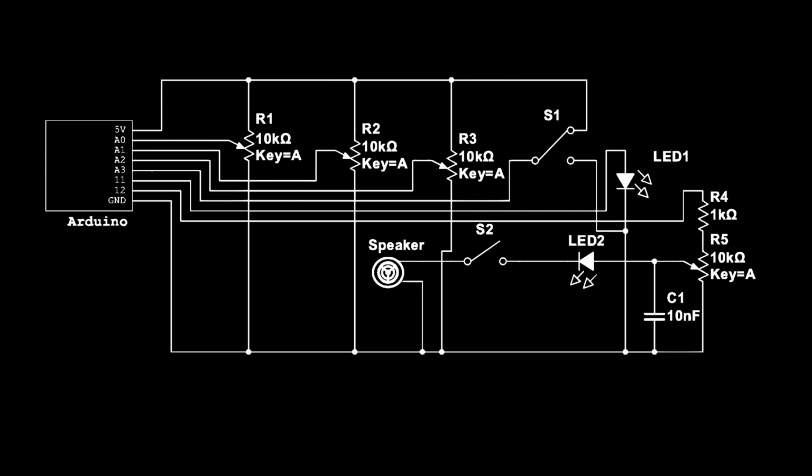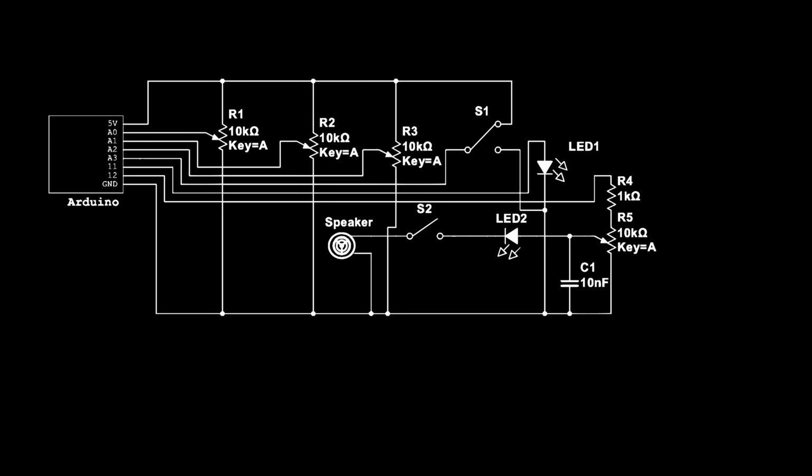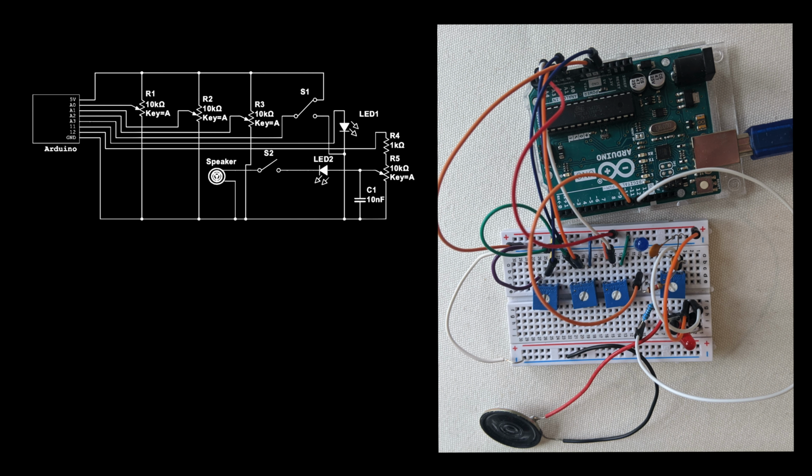Our digital synth consists of an Arduino and its corresponding input and output circuitry. The Arduino takes a voltage input which it converts into a frequency output, just like with the analog synthesizer. The digital synth uses a potentiometer knob to control this voltage input over an octave range, though it could also use a voltage divider keyboard. It has an additional switch that moves the output up an octave.